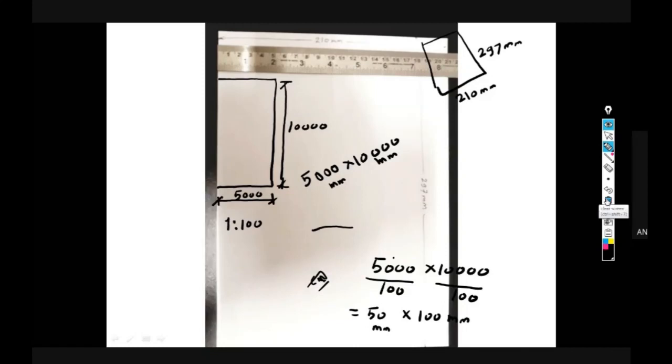Now, if I say the same plot I want to draw, but at 1:50 scale. My plot size is the same, 5000 by 10,000. But now I am asking you to draw this plot size with 1:50 scale. Now, how much will it be on the paper? It's 10 by 20, sir.